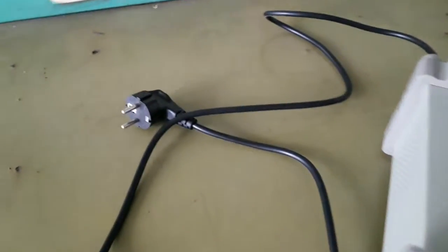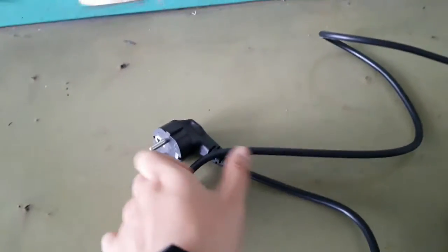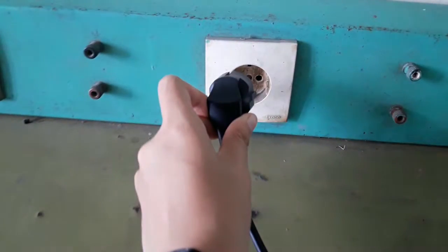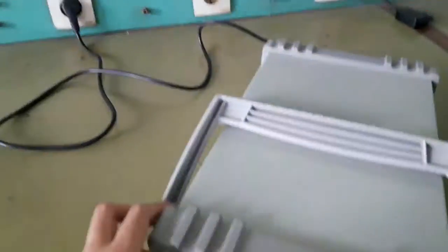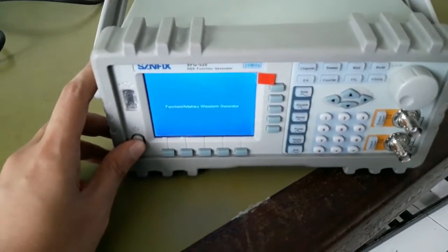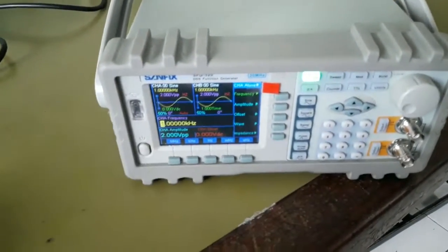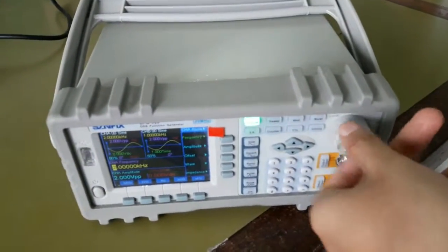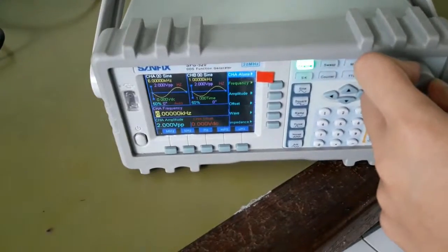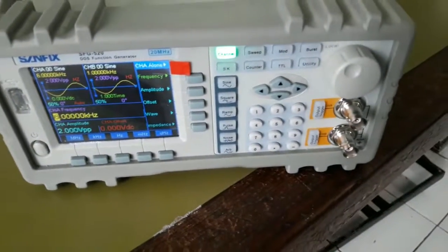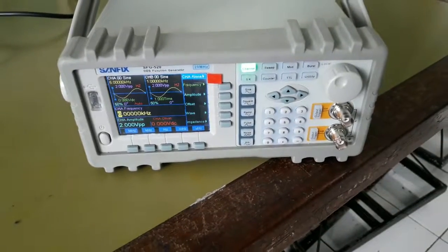And now, I want to tell about how to operate function generator. First, connect the power cable to electrical source. Second, click the power button to turn on, and the LED indicator will be on, and also display LCD frequency. Third, choose the frequency and waveform, click the button that you want to choose. Fourth, set the multiplier and duty control to identify the waveform. And now you can operate this object.